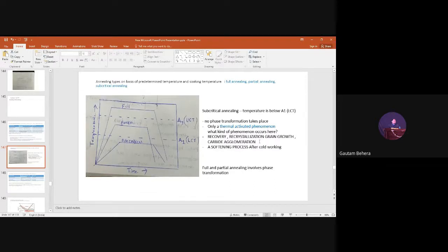If you have needle shape carbides, and in another case you have spherical carbides, which one will have more ductility and which one will have more brittleness? Needle shape more brittleness, spherical ductile. Yes, very good. Why? Can you justify that?